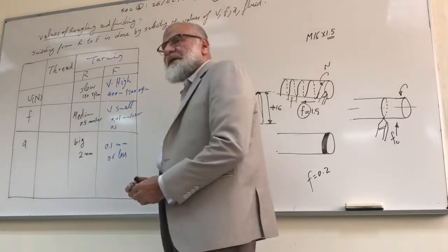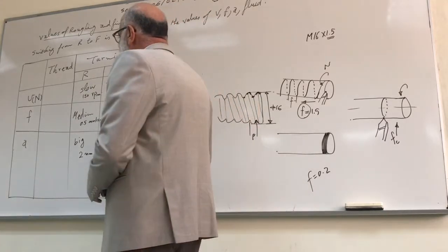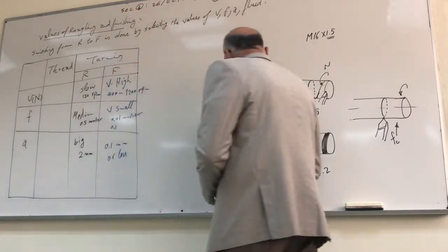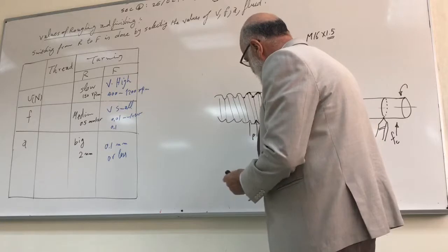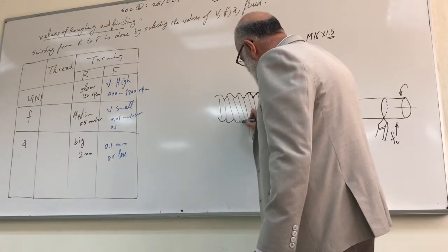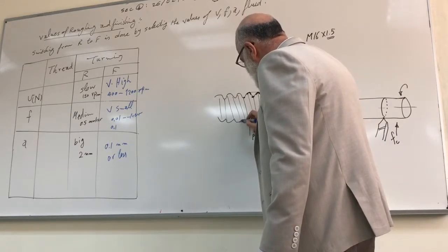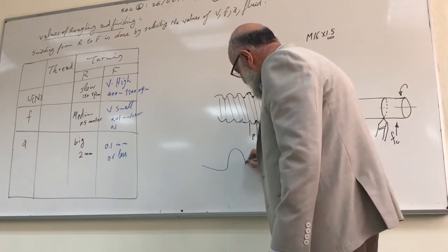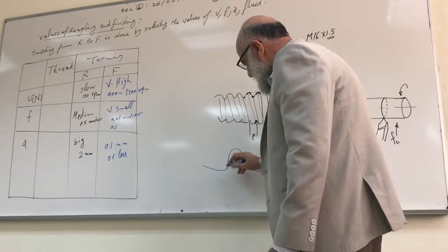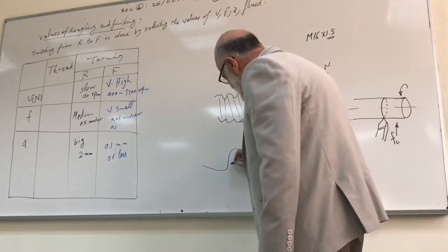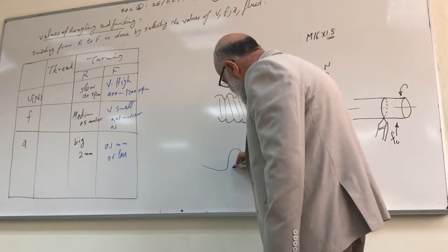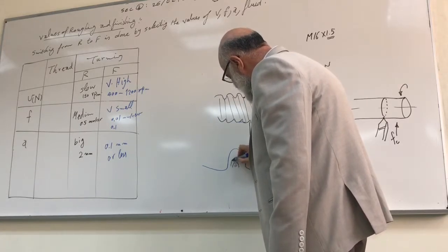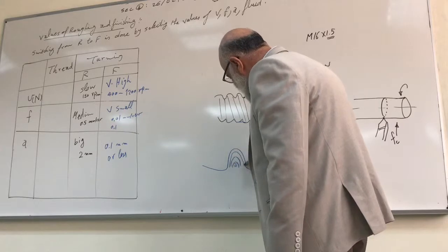Okay, what about the thread? Also thread here is done with roughing and finishing. It was like this, and we want to make this groove. Therefore, we do it many times. We do the depth in many passes. That is, we take the first cut like this. This is the first cut. Then a second cut, third cut, and so on.